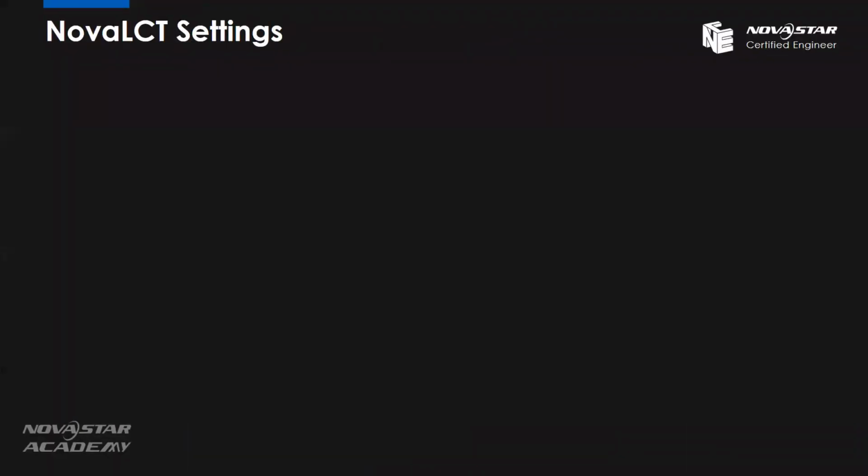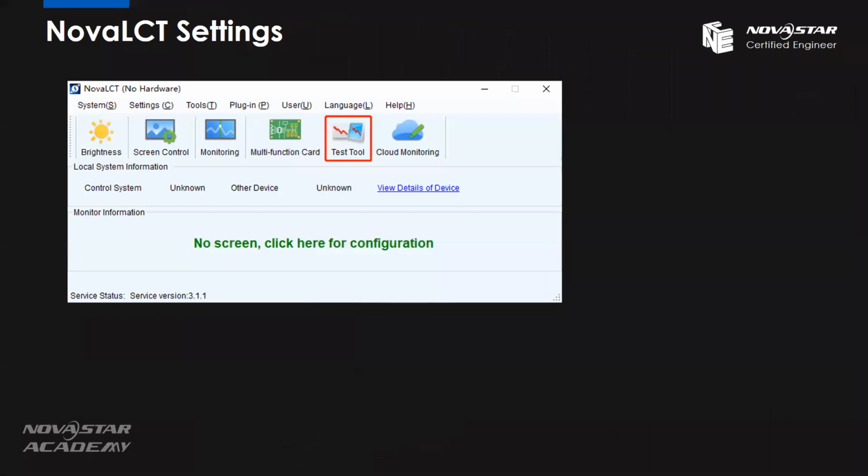And let's see, where is the tester 2 function in the software? Still in the NovaLCT, in the main interface, as you can see here, now I'm not logged in. We have the screen control and we have the tester 2 in the main interface of the NovaLCT. And we can just click the tester 2. It will pop up the tester 2 window. But sometimes you may wonder, you cannot find where the tester 2 is, because after you log in